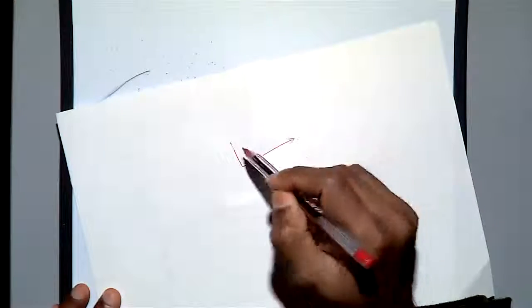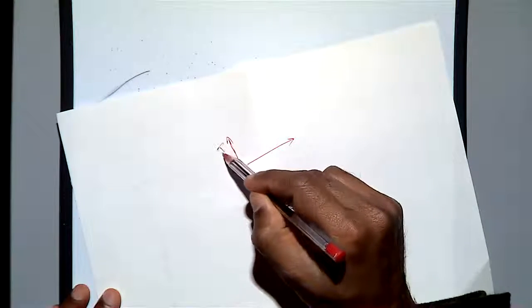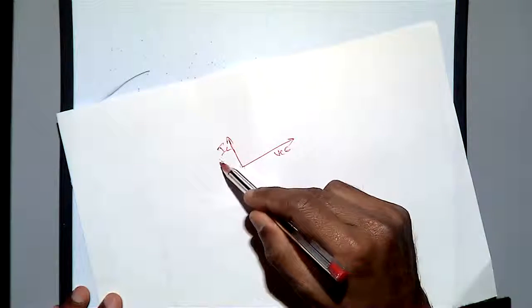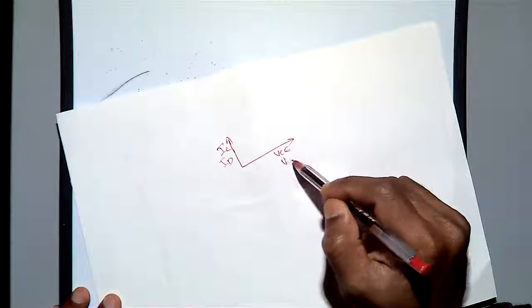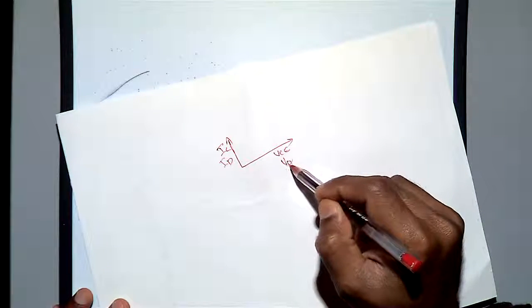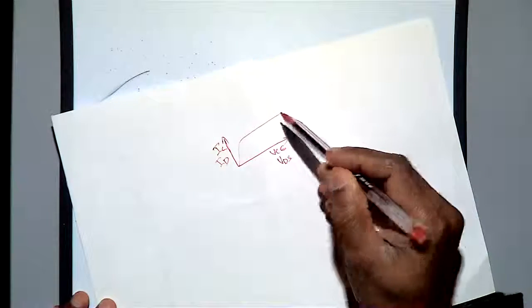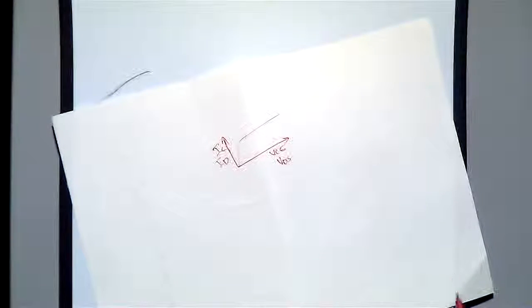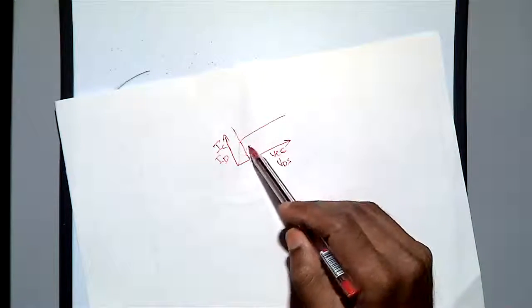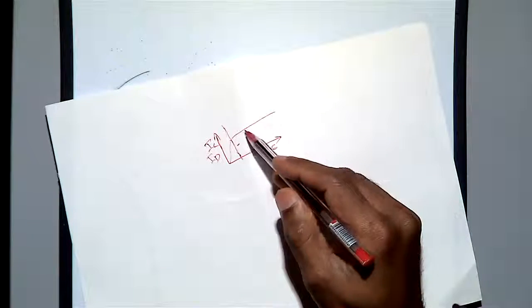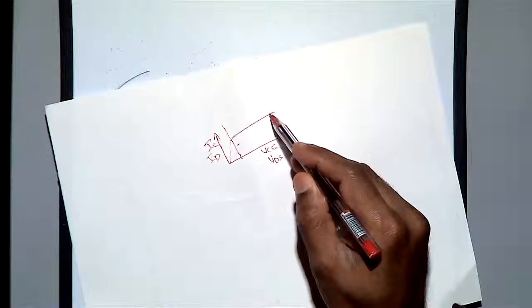Somebody decided to use a transistor as a current source, which makes sense, because when you plot IC versus VC, or ID versus VDS for a MOS, you will get something like this. You can see here the current is constant after this region. For MOS it is the saturation region; for BJT, the active region. So this region is a very good region to act as a current source.